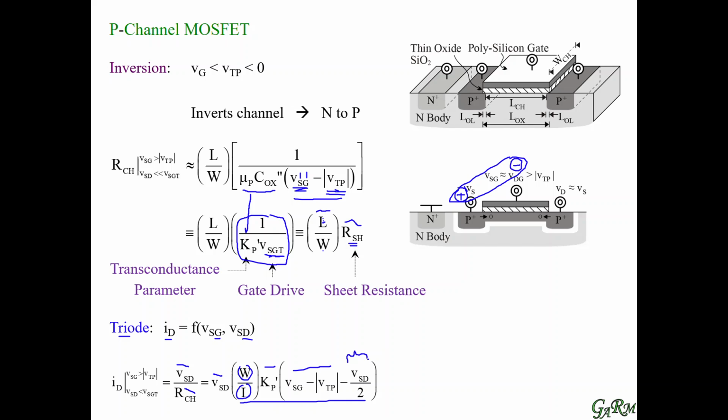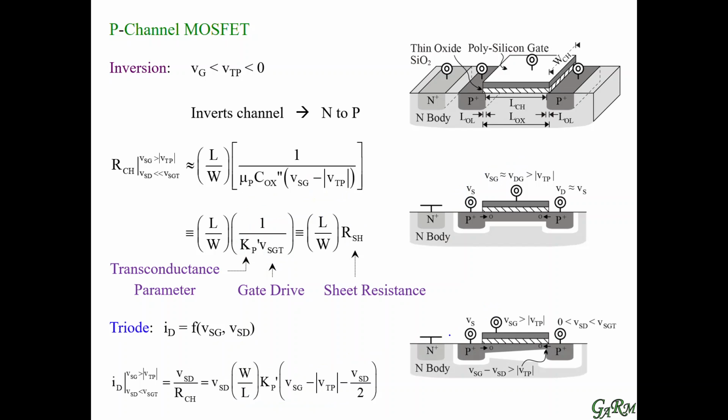This is a correcting term, and let us see what that is referring to here. So remember, we're going to ground this side. We're going to apply negative voltage here. But what we're saying here is that we can apply also a negative voltage here. So on the left-hand side, we have a large negative voltage, so we have a lot of charge underneath the gate oxide.